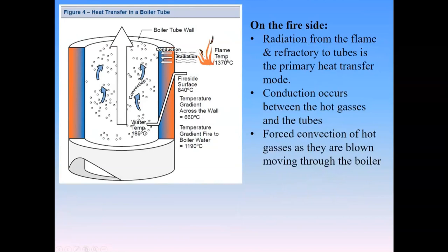The flame here is going to create radiation that's going to then absorb into the metal of the walls of the boiler. Okay, and in this case, if the radiation goes to just bare metal tubes, it would get so hot that it would start to melt some of these tubes. So in order to keep them cool, we have to keep water in these tubes, and the water does two things. One, it picks up the heat, which is great, but it also means that it can keep the metal cold enough so that it's structurally strong to support the pressures that the tubes are operating.